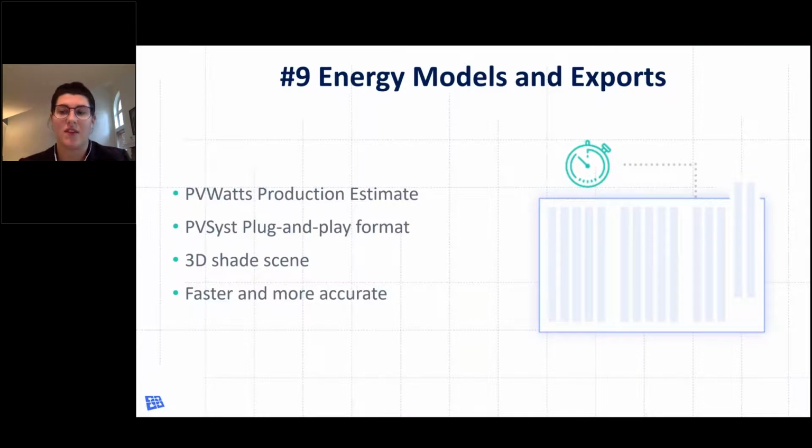The last thing in PVCAD Mega is energy models and export. So it does use PVWatts similar to PVSketch Mega, and you can get those in applications, but we actually do go a step further by providing a PVSyst export in a plug-and-play format. This basically provides a 3D shade scene to use in PVSyst and allows you to get modeling in PVSyst faster with more accuracy.